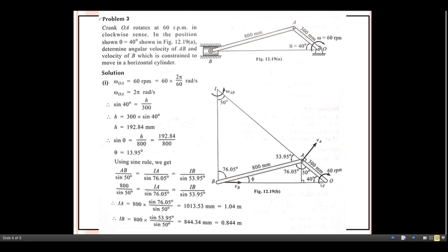So this angle is 40 degrees. First of all, complete this diagram. Now what about this 40-degree angle? If you focus on this angle of 40 degrees, first, as per the motion of this link, complete the location of the instantaneous center. Then we'll come back towards the geometry of this one to see how we can get the angles.